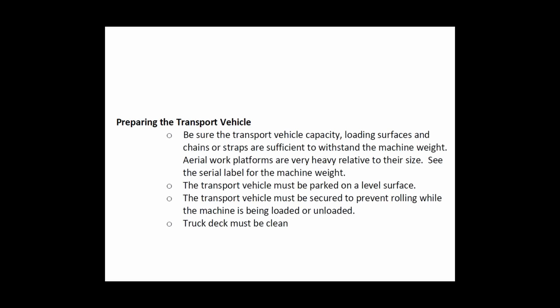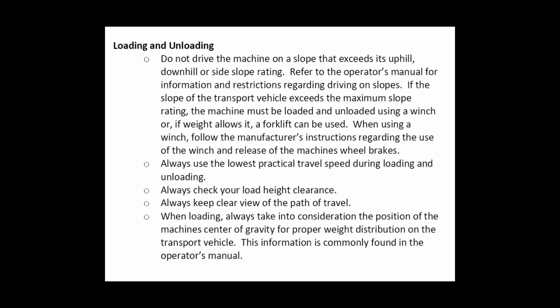The transport vehicle needs to be parked on a level surface. The vehicle must be secured to prevent rolling. Whether we're loading and unloading at a dock or on the ground, we need to make sure that the transport vehicle is secured from moving around while loading and unloading this dynamic movement of equipment on and off the truck. And again, the truck deck must be clean to prevent slipping and tripping hazards or loss of traction of the machine loading and unloading.